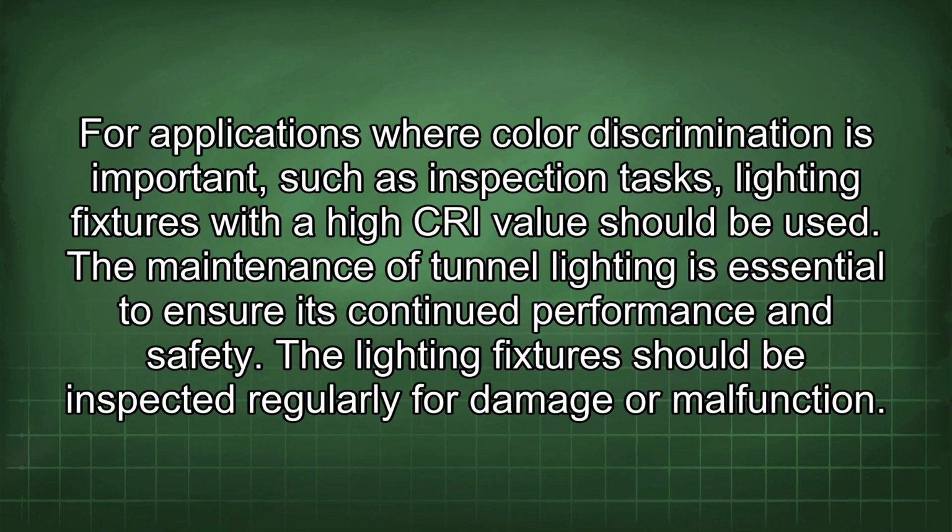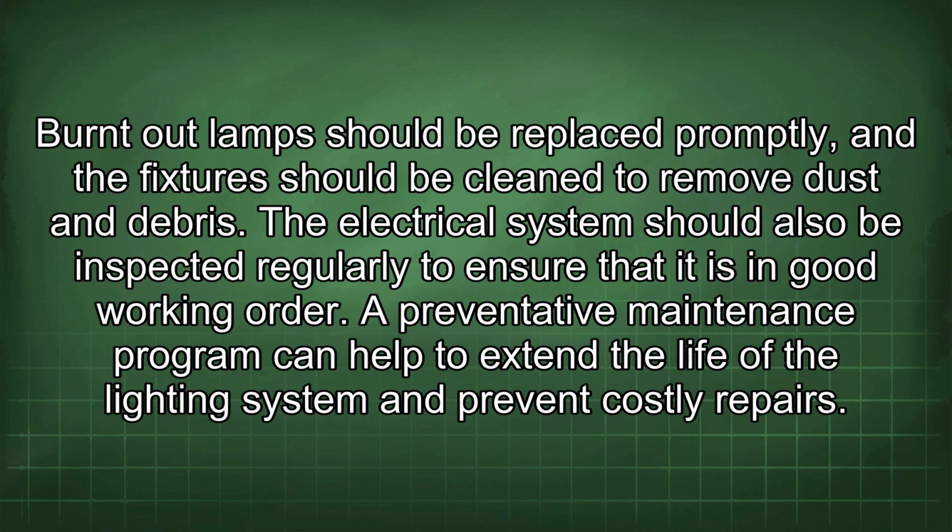For applications where color discrimination is important, such as inspection tasks, lighting fixtures with a high CRI value should be used. The maintenance of tunnel lighting is essential to ensure its continued performance and safety. The lighting fixtures should be inspected regularly for damage or malfunction. Burnt-out lamps should be replaced promptly, and the fixtures should be cleaned to remove dust and debris.